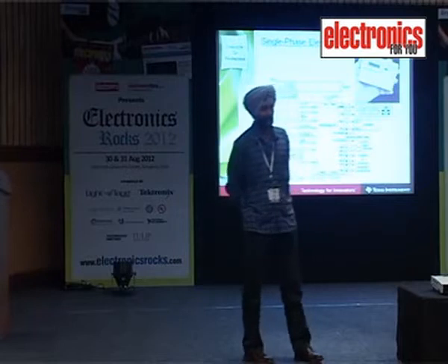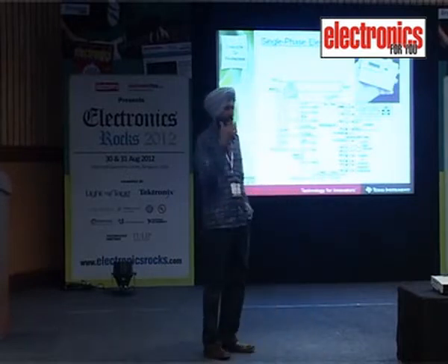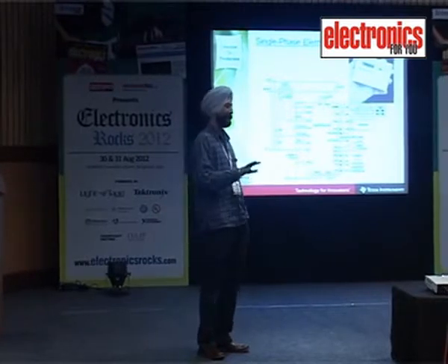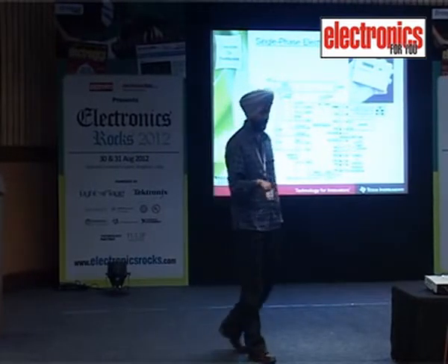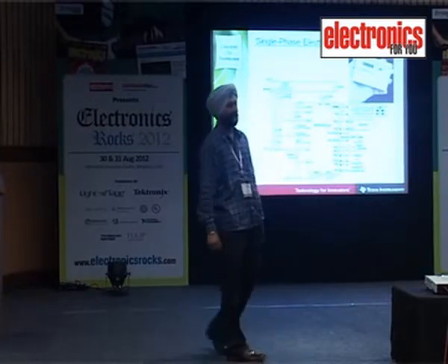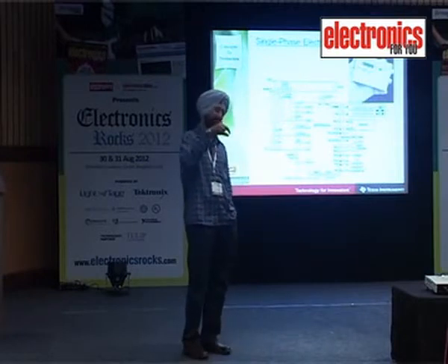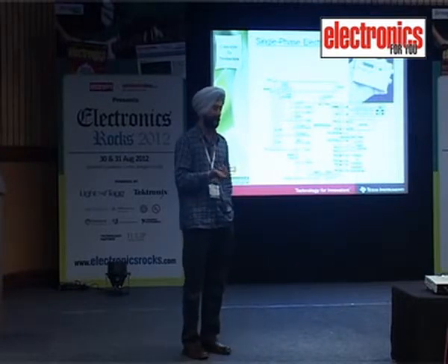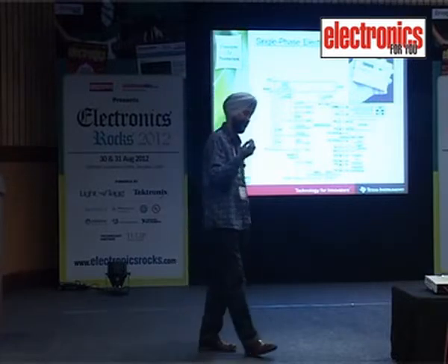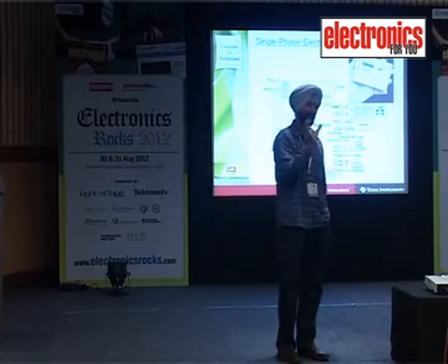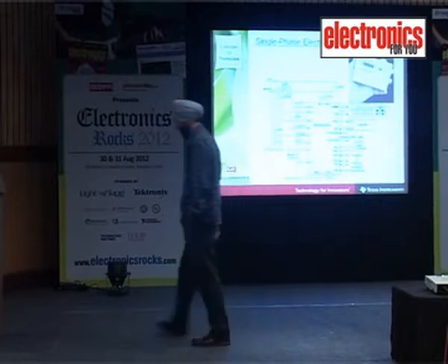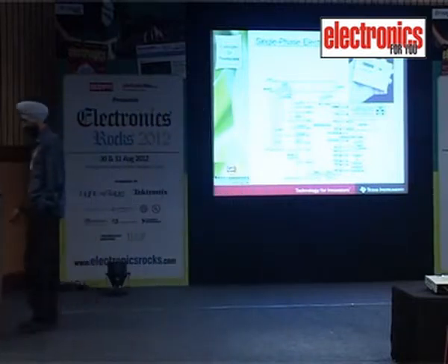Maybe there are others, you have ST, you have Analog Devices, but most of the energy meters, in the industrial as well as the domestic segment, are powered by MSP430, because these chipsets have a special ASIC inside the MSP430 which takes care of measurements like active power and power factor. All these things are taken care of by the ASIC, and the rest of the stuff, maybe the housekeeping, display, and communication, is taken care of by the MSP430's normal generic CPU core and peripherals.